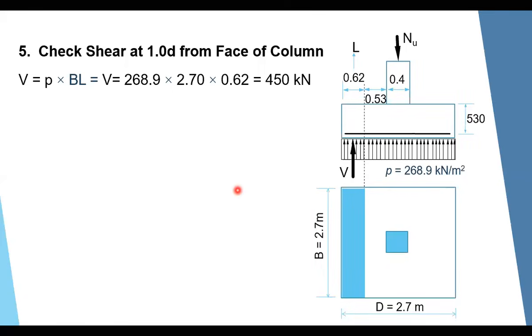If you go back to my videos about slabs, you'll find that always when we check the shear, it is very safe, very safe. So sometimes you will not need to check for shear, but in the footing, it is very important to check for the direct shear or one-way shear, and also check for the punching shear, because it can result in a collapse of the footing if you didn't check the shear.